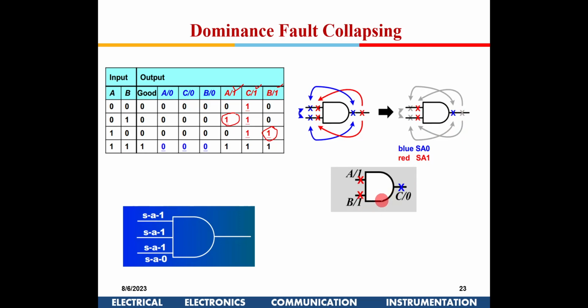So what the algorithm first does is it will keep moving everything to the primary inputs if there are many gates. So stuck at 1 here, stuck at 1 here, stuck at 1 here, and stuck at 0 here for a 3 input AND gate. These are the only 4 vectors which are good enough to check this gate. Are you all in agreement with this? For an AND gate, if I do this testing, will it detect everything? 4 into 2, 8. So instead of 8, I just have these 4 test vectors. Is it good enough?